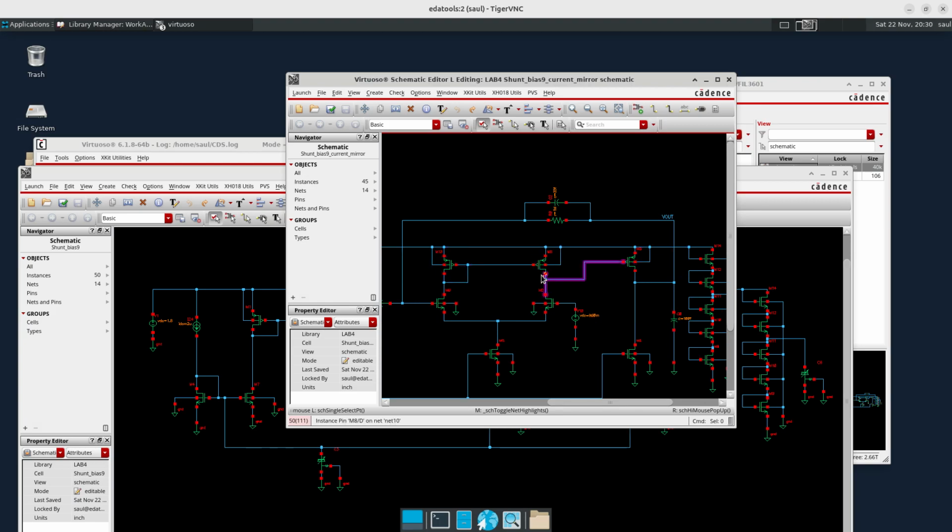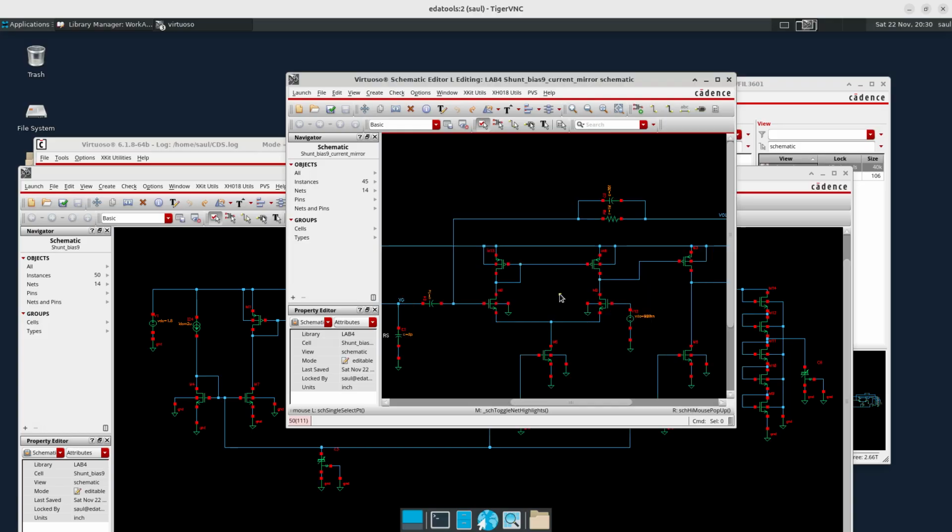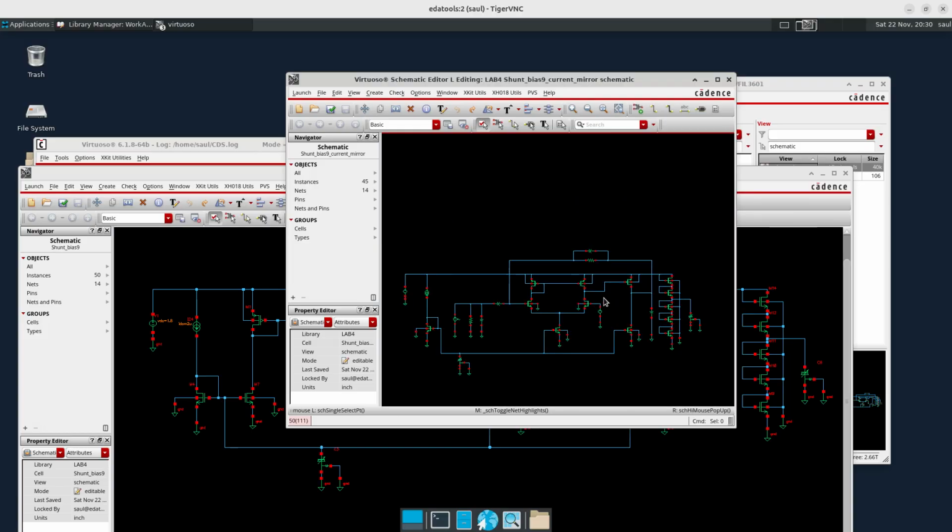So it is basically subtracted here at the output, which is something very positive. So the noise of M5 does not propagate. We will run some simulation to see that it has a little bit better noise performance because of that, and the biasing is of course simplified.